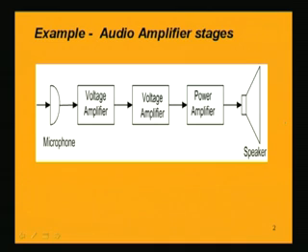So at the last stage, the amplifier being used is a power amplifier or large signal amplifier. That amplifier handles a higher amount of voltage and current, because the multiplication of voltage and current gives you the power. So in that amplifier we have a power transistor.